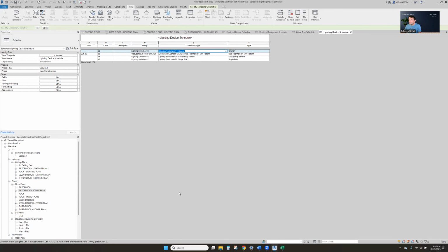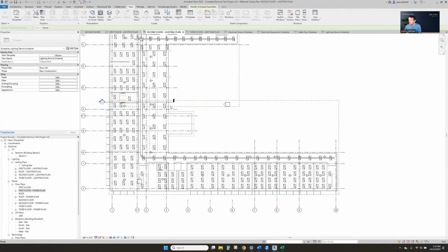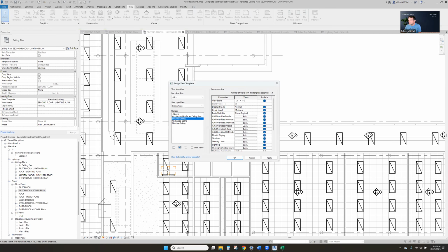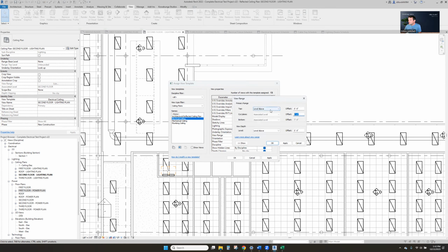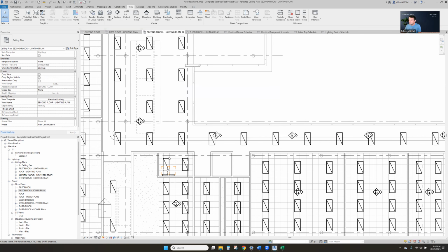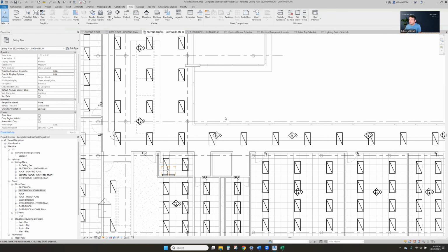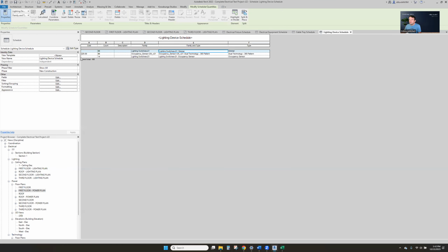And once these are all built for your project, right, now it becomes, again, like if we deleted every single pole switch in the model. So let's go to a lighting plan. Let's make sure that our view template is set to 4 feet so we can see the doors. So now if we went and deleted every single pole switch, right, it's not going to show up anymore. If I undid that, we're going to have them again. So real-time data that you can pull and then update your spreadsheets accordingly, and pricing gets updated kind of automatically. So big benefit, especially on design build projects.